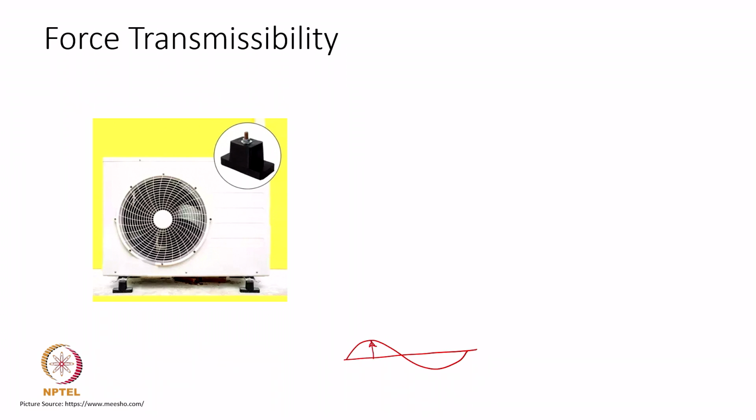that amplitude, if the vehicle is moving at a very slow speed, the mass will undergo an amplitude that will match with the profile of the base, right, or the road profile. But if this speed increases, this amplitude itself is going to be much larger, right, than the amplitude of the base excitation. So, if this is x, the amplitude y with which this inertial mass vibrates, that amplitude y will be many times more than the input amplitude x. That is what the base or the displacement transmissibility that we have seen. Okay. So, that was discussed as the displacement transmissibility.